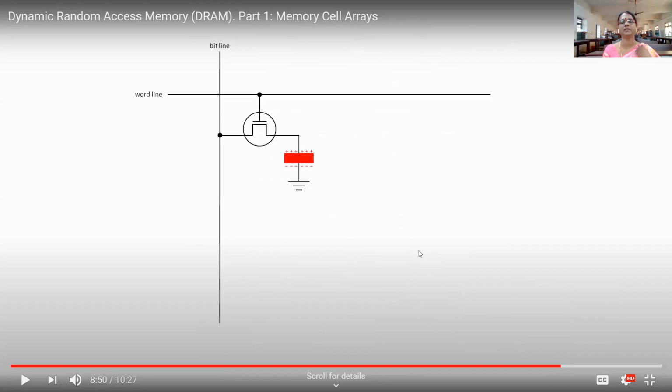See, this is one peculiar property of this dynamic random cell. What happens? See, we are considering one single cell. What happens is if it is fully charged, even though there is no charge in the bit line or the word line, this slowly starts to discharge to the bit line. Okay, through its source it starts to discharge.